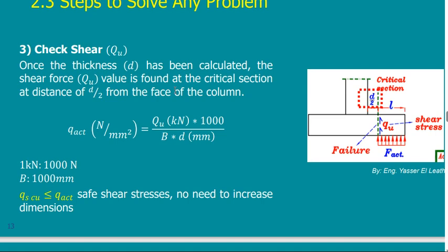It means that when I calculate the amount of steel, it is also the amount of steel in this 1 meter. Suppose I have a width of 2.5 meters, then the amount of steel should also be multiplied by 2.5. It is not only the amount that was calculated for the 1 meter. This is very, very important for all of us.